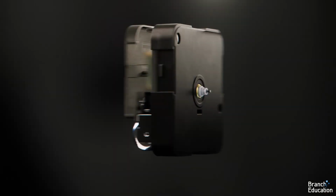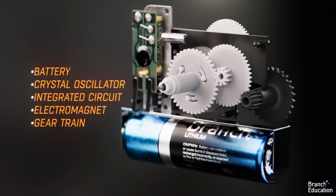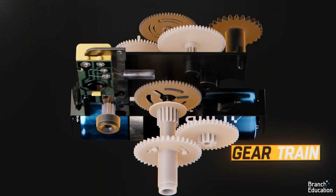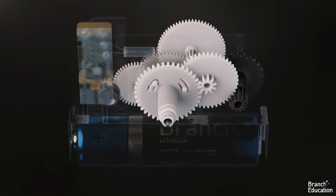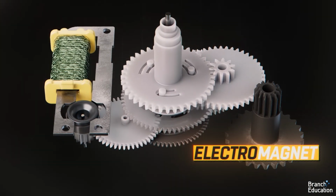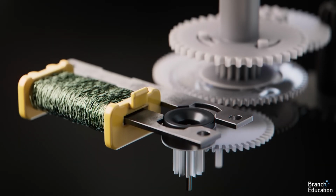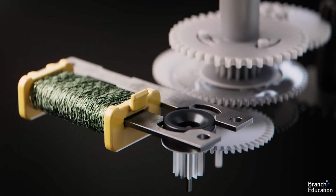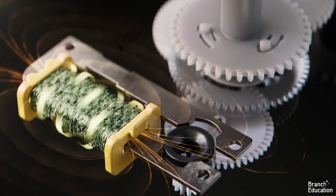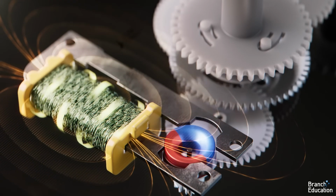Inside this $10 wall clock are 5 unique systems that enable it to work. The most recognizable is the gear train made from 8 gears. At the beginning of the gear train, a driver gear is rotated by an electromagnet, which provides the force to rotate the clock hands. This electromagnet is composed of a coil of wire, which uses electrical current to generate a magnetic field, and a strip of iron to channel that magnetic field to the drive gear.